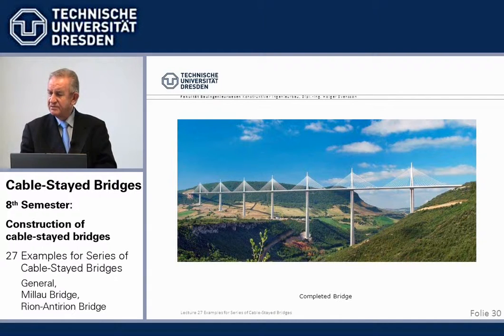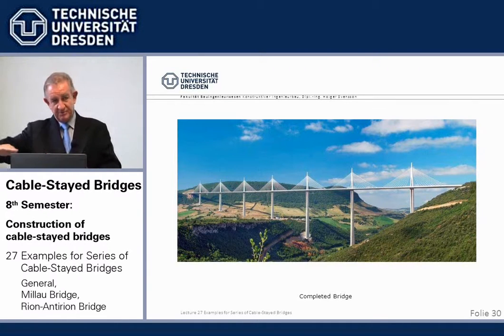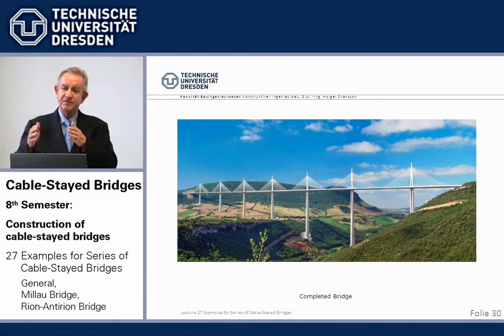And construction, the launching itself on 342-meter end spans is something. Then we launch 4 meters too high to save the money and bend it down. And we have the final towers modified as auxiliary supports at the tip. Those are quite a number of outstanding ideas coming together in one bridge. Normally, everybody is quite proud if he has one good idea, which he can apply in a bridge, but they had several here, so I admire that very much.